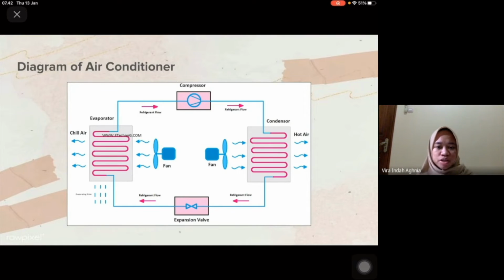There are several components in the air conditioning system, including the compressor, condenser coil, evaporator, air handler and blowing unit, and thermostat. The compressor functions together with a substance called working fluid that can easily transform from gas into a liquid. The main task of the compressor is to convert low pressure gas into a high pressure gas, which also has high temperature. The condenser coil has a fan fitted into it which cools down the high pressure gas and converts it back into a liquid. The evaporator is located inside the house and is usually found near the furnace. It is connected to the condenser with a very thin pipe.